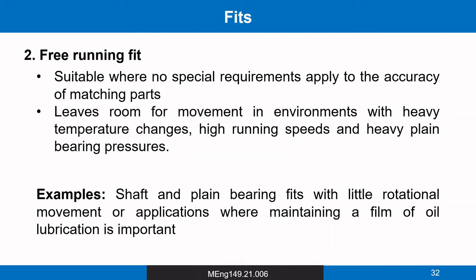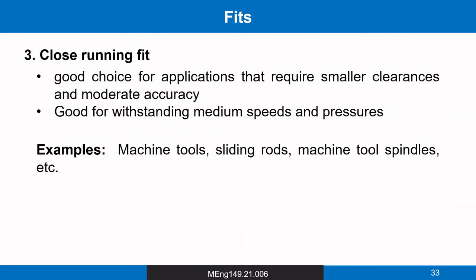Okay, so that's the free running fit. The close running fit is a good choice for applications that require smaller clearances and moderate accuracy. This is good for withstanding medium speeds and pressures. Okay, so it has smaller clearances compared to the free running or the loose running.